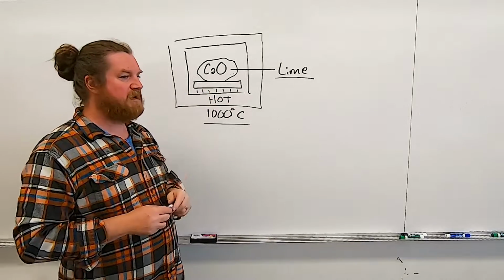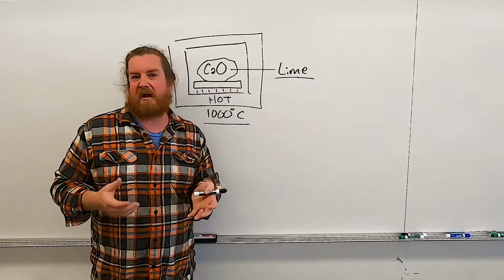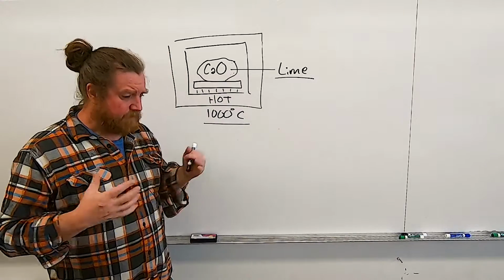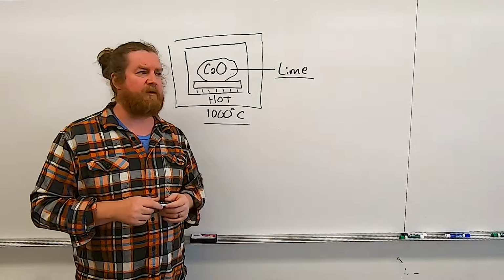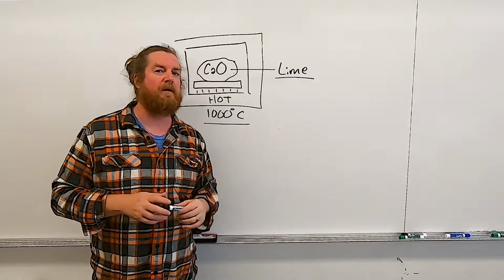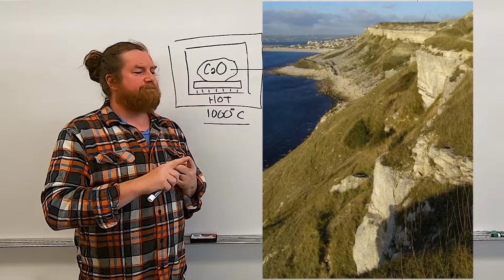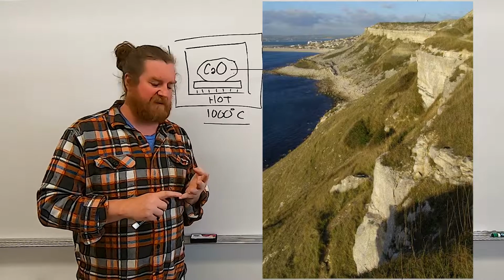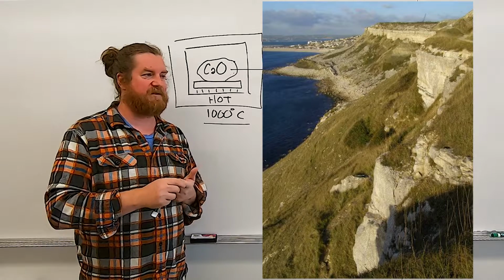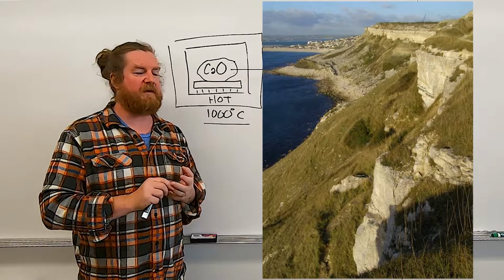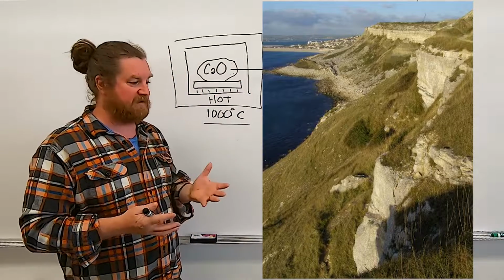But to get to real concrete, we need to have some other additives. And again, this is a little bit magical, right? So these are the limestone that crops out near the town of Portland in England, not Portland, Oregon, or Portland, Maine, but Portland, England, OG Portland, if you will. That tends to have the right kind of other stuff, if that makes sense. So it turns out there's a certain type of clay that needs to be there in a concentration of about 10%. There are a few other things that need to be kilned with this lime to make it so that when you mix it with water, it will react and solidify.